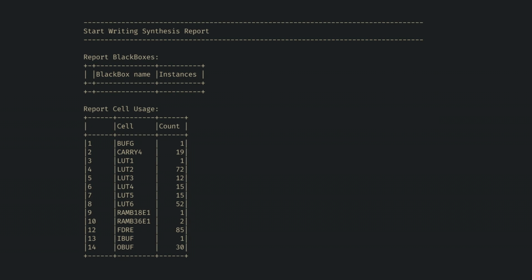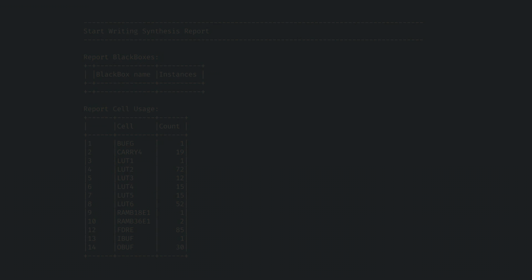It's good to roughly check over this and make sure nothing crazy is done, especially if you're using RAMs, because sometimes you'll define a RAM in a way that can't be done using the built-in hard RAMs, and your entire programmable circuit will be used creating your exotic RAM by mistake. Speaking of RAMs, that was my next experiment.